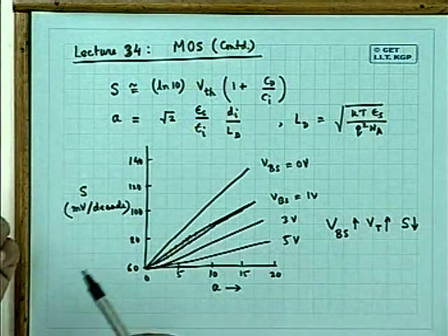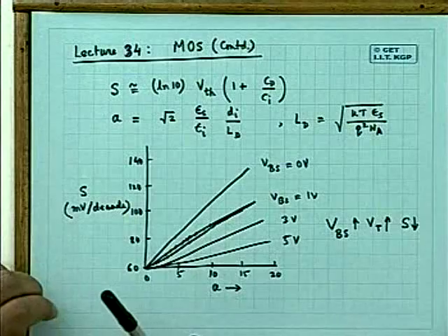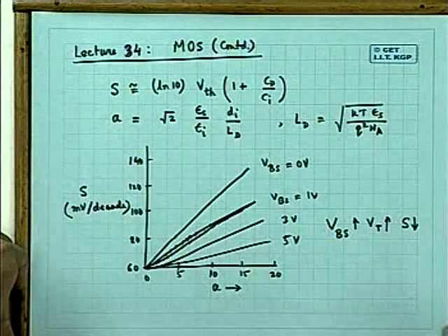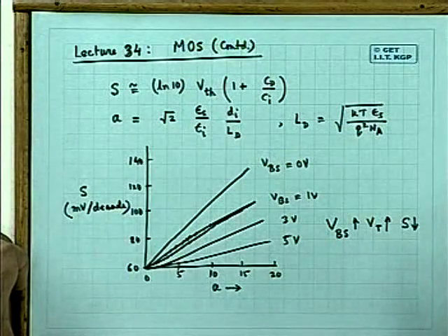So remember the inverter circuit where I told that the driver does not suffer from any substrate bias or body effect, whereas the load suffers from the body effect. Threshold voltage is increased due to the body effect, and it becomes a function of the input-output swing. But in one respect it is greater because the subthreshold slope is reduced. Therefore, such a load in the inverter circuit can better function at a lower threshold voltage, at a lower driving voltage.